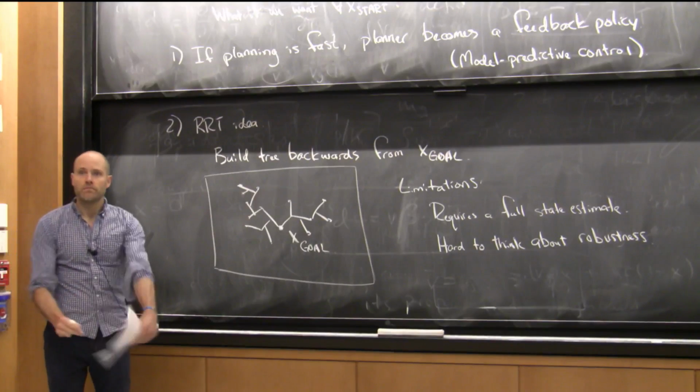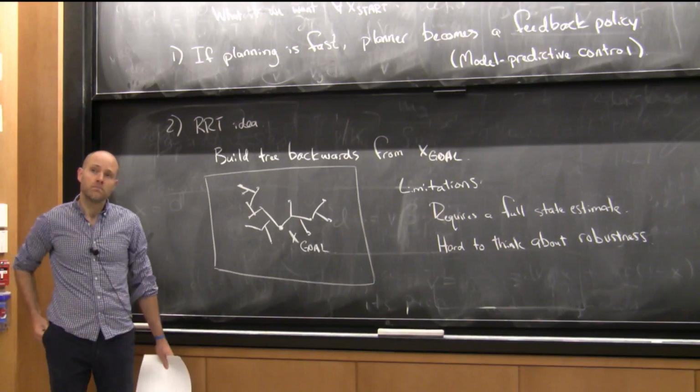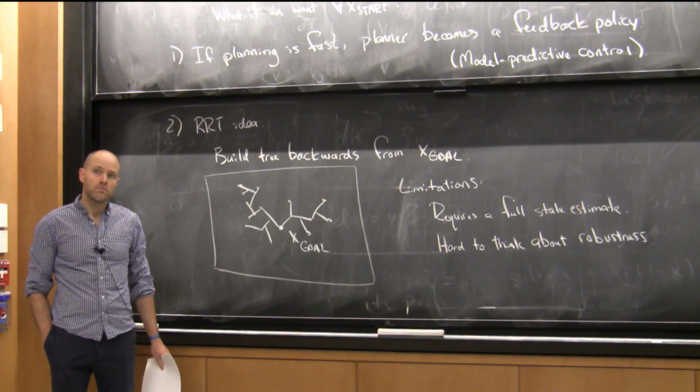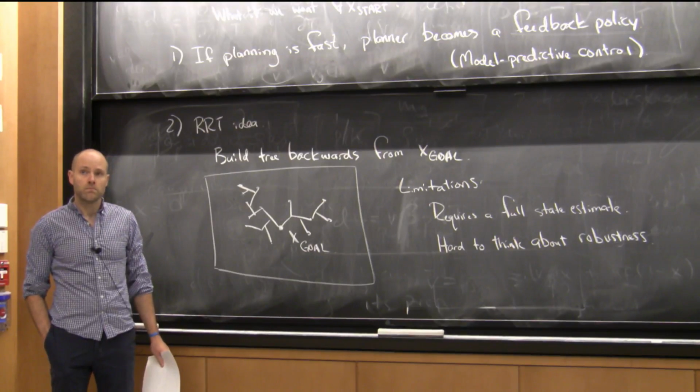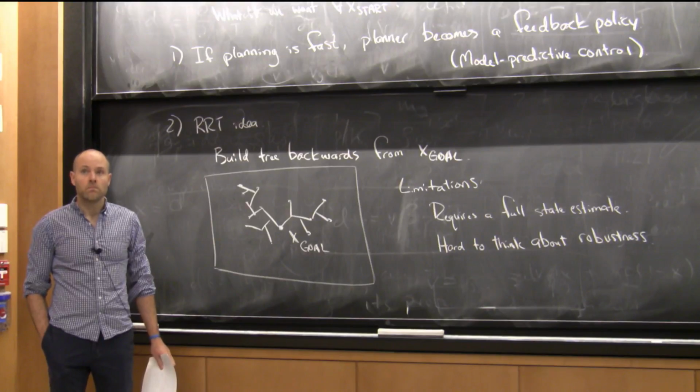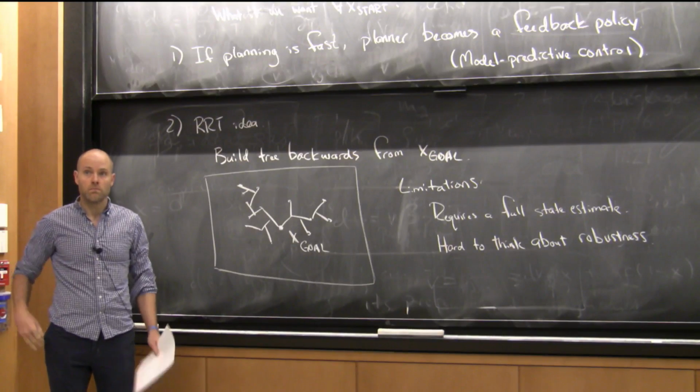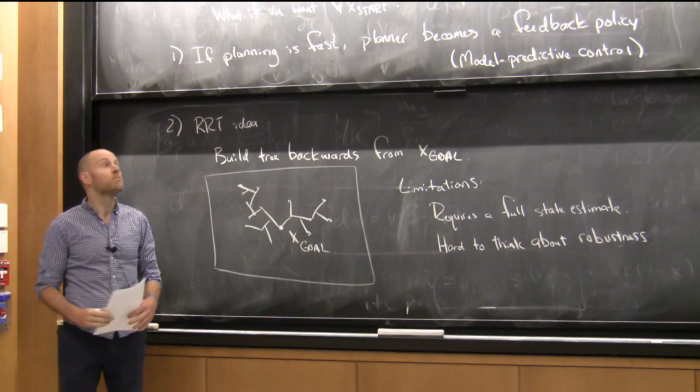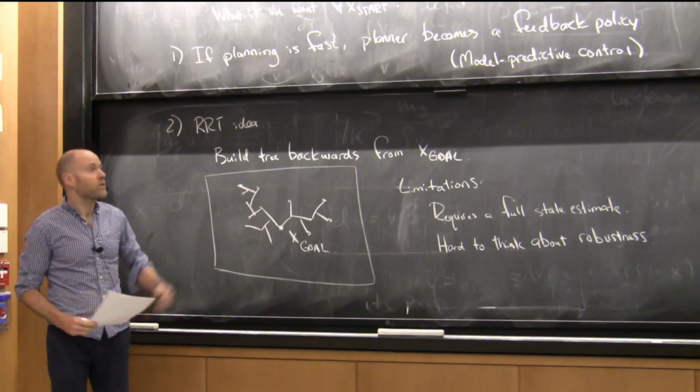Yes? So I agree the traditional RRT is going from point to point and the edge is just a path segment. But if you generalize the node to represent a region of configuration space, and then your edge is this concept that it can go from a region to a region, and it's robust, then it seems like you could talk about some robustness. I don't know what the formal guarantees would be, but you can think about robustness in this concept of RRT.